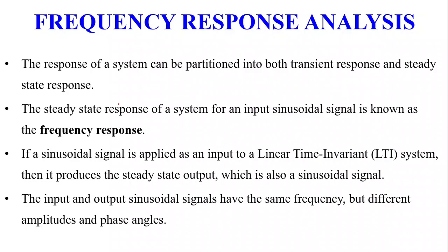Now let us talk about the frequency response analysis. In general, the response of a system can be partitioned into transient response and steady state response. The transient response can be found by applying the Fourier integrals to the given transfer function of the system. The next one is frequency response. The steady state response of a system to a sinusoidal signal is known as frequency response.